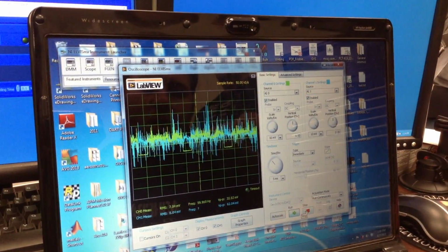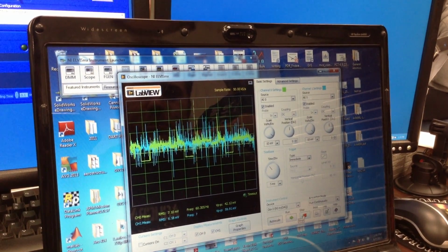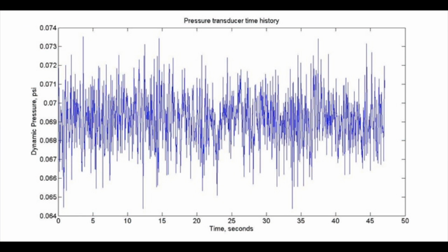After a steady frequency is set, the logging feature is activated on the data logging system. Stop the log once a minute has passed and then process the data by graphing the points against time. What is seen in the graph is voltage versus time. This can be converted over to velocity by using the equation for equivalent airspeed and conversion of the pressure transducer. Plotting this information gets velocity versus time.